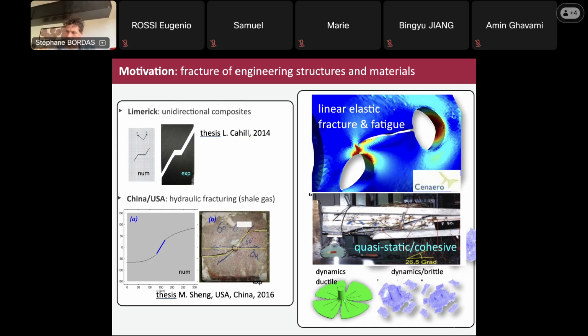So you put them there because you want concrete to be able to withstand tensile loads, not only compressive loads. Concrete is extremely good in compression, meaning that you can really push on it like crazy and nothing will happen. It's very difficult to break concrete in compression. It's very easy to break concrete in tension. So if you take a specimen and you pull on it on both sides, it's going to break immediately. There is a very small resistance to tensile stresses.